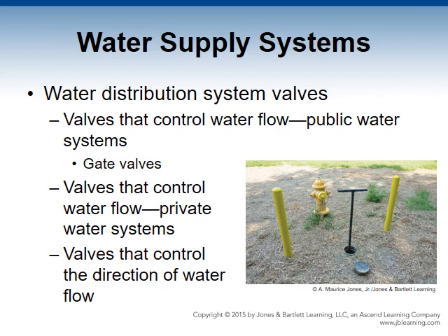The backflow prevention devices. These are double check valve assemblies. These devices contain two independent spring-loaded check valves that open when there is 1 pound per square inch of pressure difference between the flow. The first check valve closes if there is a back siphonage due to reverse flow. The second valve closes when the back pressure occurs.